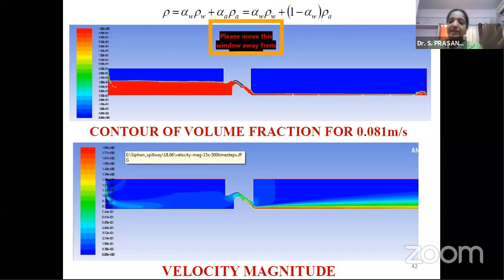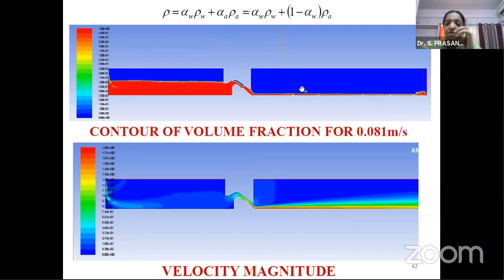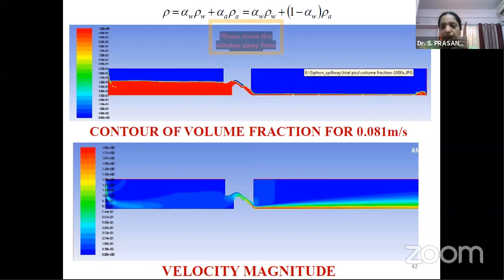Second is also an air. But in this case, in most of the open channel flows and pipe flows, we have water or oil or any liquid that is moving, that becomes the primary. So in my case, water is primary, air is secondary. So when I say primary as water, the primary liquid is initialized with 1 and the secondary liquid is initialized with 0. And anything in between 0 and 1 is the mixture of these two phases, that is multi-phase, air and water.